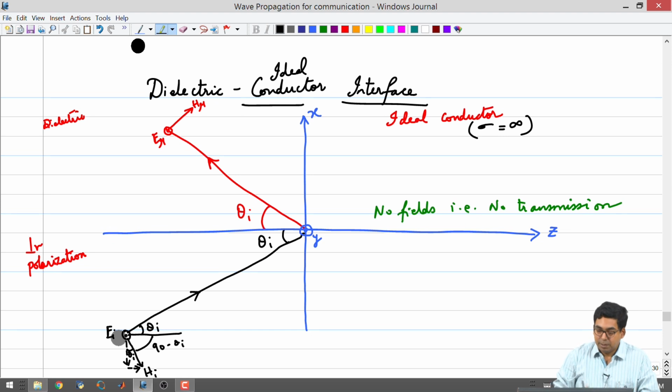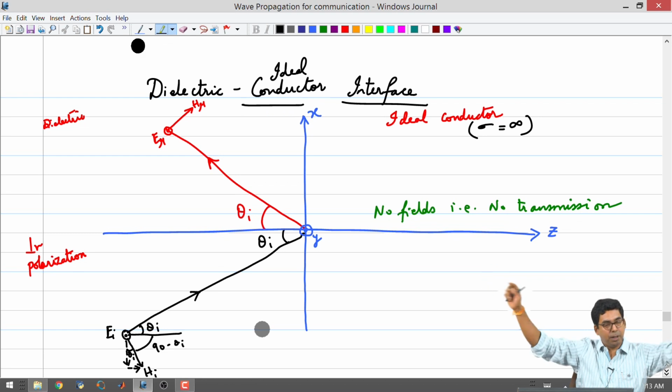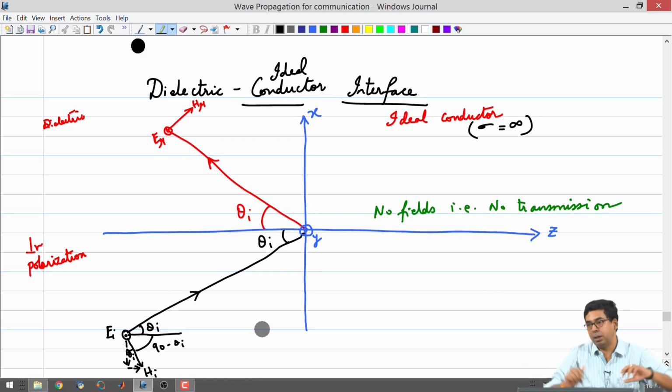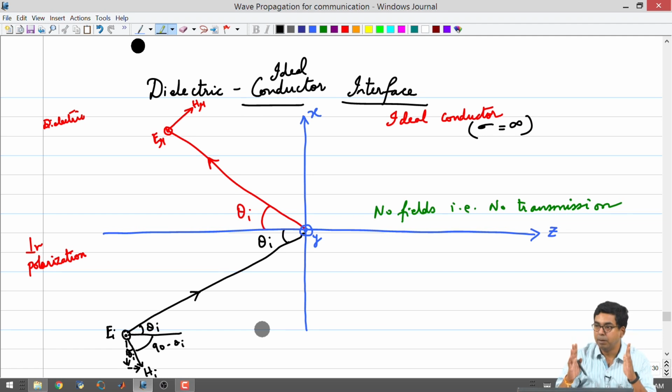Another way of thinking about it is, if you did launch a wave on one end of a parallel plate configuration, you will notice the wave emerging out of this parallel plate configuration on the other side, without diverging, without going out of this region at all. So, since this wave is completely being guided from a source to an end by merely using two parallel plates, such a configuration is known as a parallel plate waveguide.